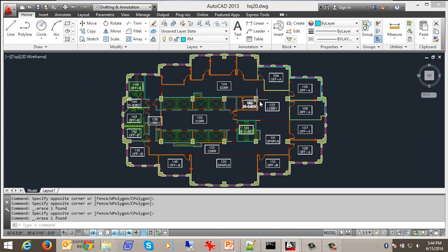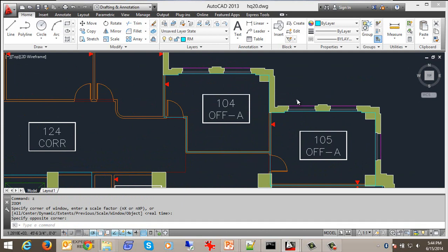So that's an example of a polyline. Now, obviously, you're going to go around room by room in order to draw out your space. Here, for example, I've got an office, so I'm just going to zoom in to this office. I have an existing polyline, which I just highlighted here, depicting that space, and it's on the corresponding room layer, and it's a closed polyline. This is the sort of space that you want to start depicting for each one of your different rooms and each one of your different workstations, depending on how far down you want to go.